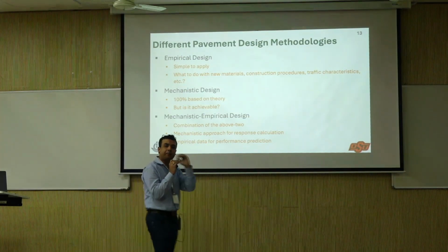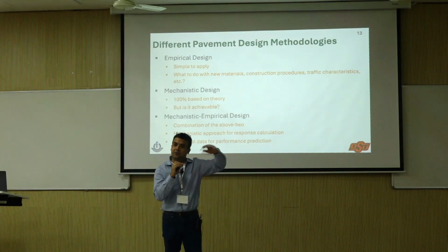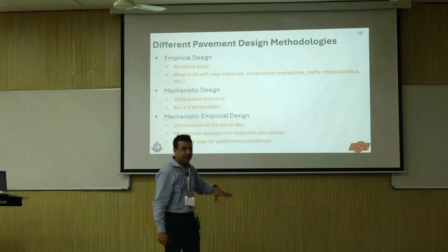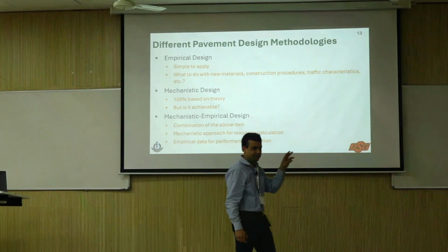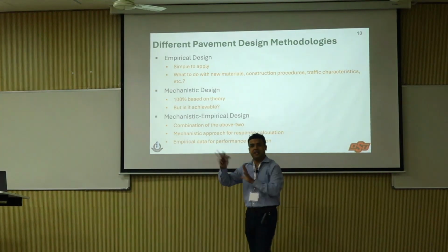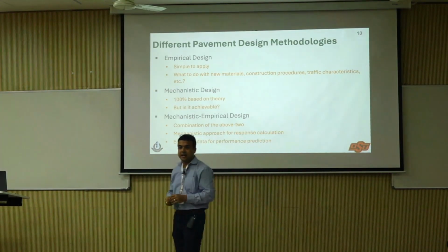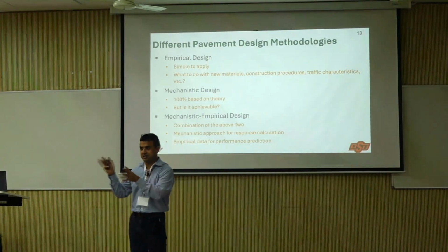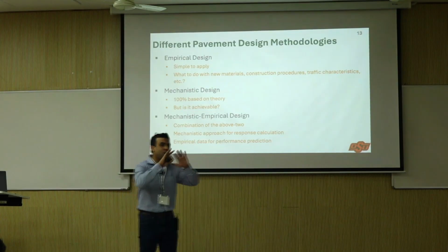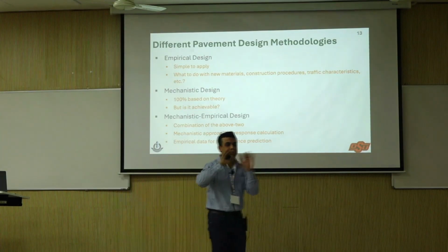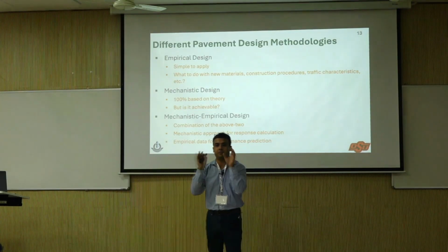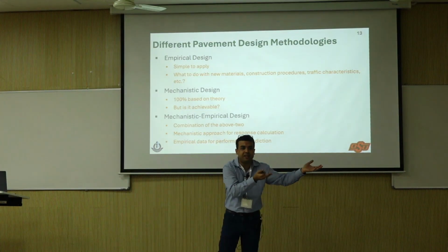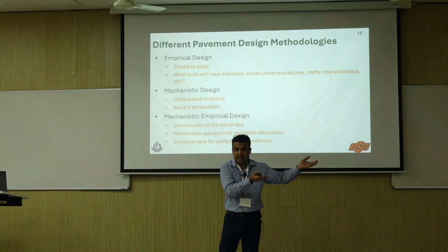Mix design approach keeps changing with time. There is something called volumetric mix design, which was called Superpave, which is VMA, VFA, and all of that stuff. Now there is something called balanced mix design, or performance based mix design. I'm not going to go into all the details because not everybody here is an asphalt person, but the point is you are changing your material input significantly as well.